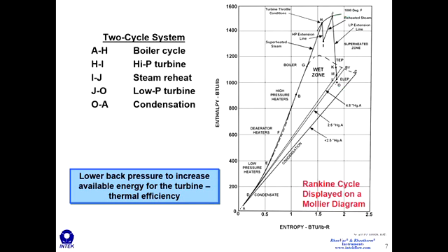So lowering the condenser pressure directly correlates to generating more megawatts. And then as we complete the cycle, the steam goes through an instantaneous phase change on the condenser tubes, and we dump all that heat that we added in the boiler and all the low pressure feed water heaters out to the environment, to the cooling towers, to the air, or into a river or cooling water pond or wherever the water source is. So there's a tremendous amount of energy that's discharged. It's a waste product.